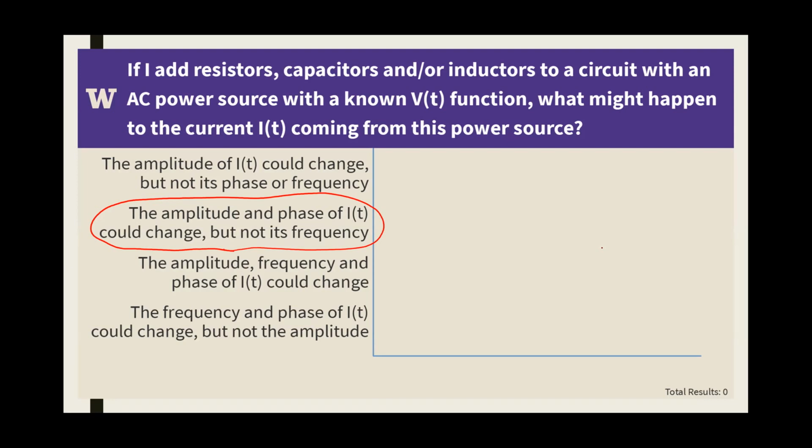So you want to be careful, because that was an equation from the oscillating circuits. So those were circuits that we had no driving power source. So if I have an inductor and a capacitor but no power source, they'll have a natural frequency of oscillation that depends on L and C. But if I have a power source in these AC circuits that's driving with a certain omega, we'll always be oscillating at that omega that I'm driving it at. Gotcha.